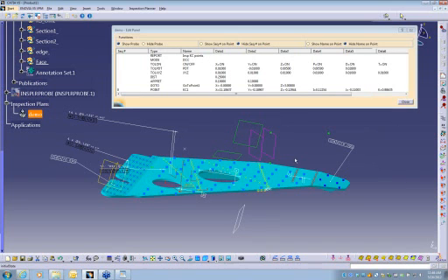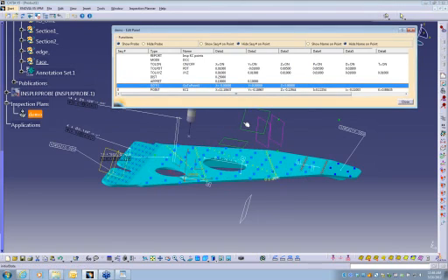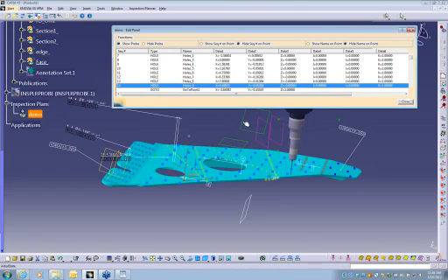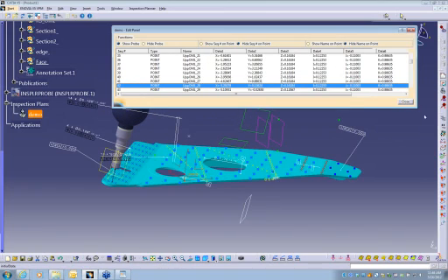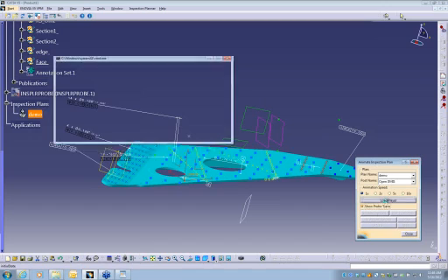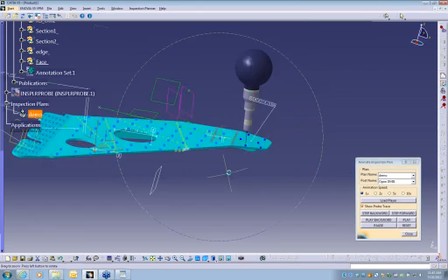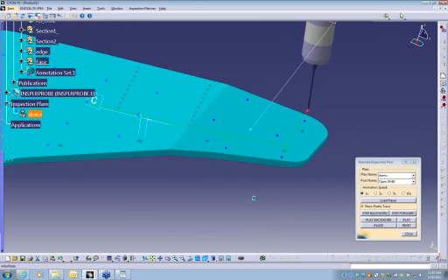Okay, go ahead. So we have our program here. We can go down on our keyboard and just hit the down key and go through our whole program. That's a quick and dirty way that we can simulate the program. We can also hit this button right here and say that we want to simulate. We want to show the trace, we want to load the player, and we want to say play. So that is actually putting the probe trace and showing exactly what's going to be measured.